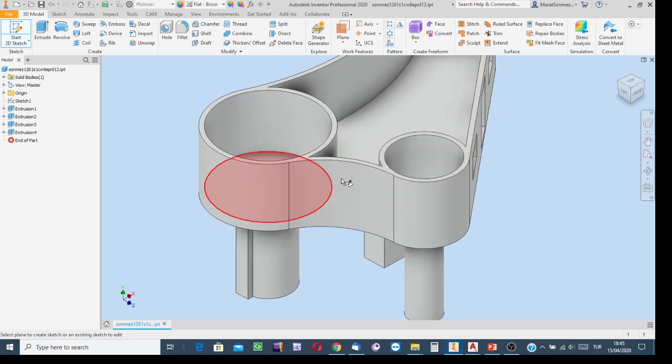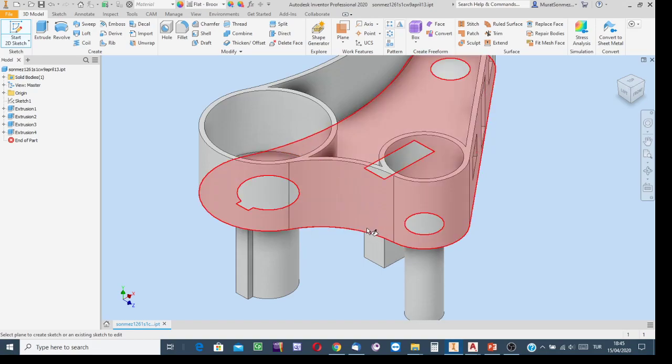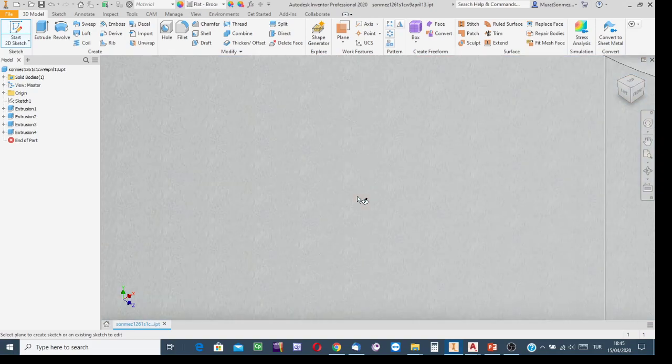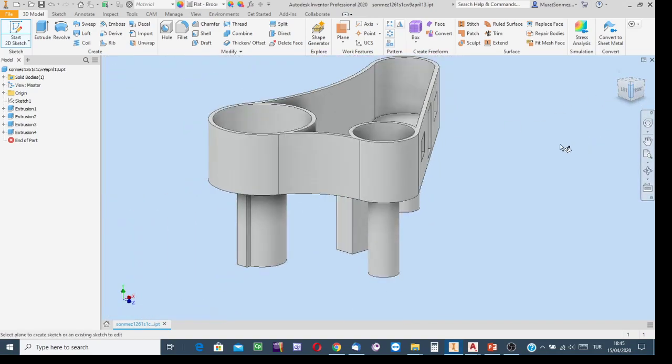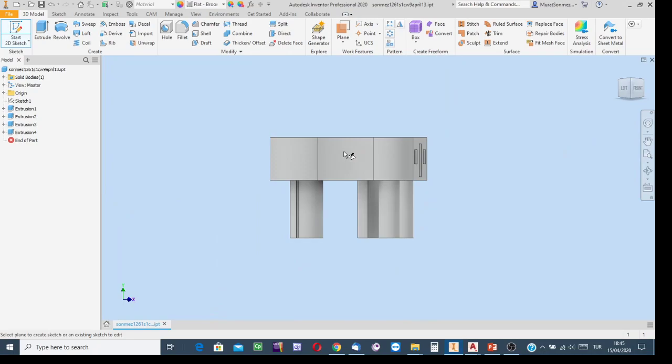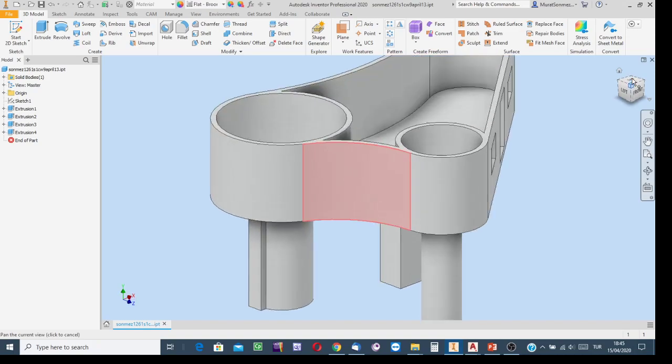Okay, it cannot find the sketch plane because the surface is a curved surface. If the surface is not a flat surface, you cannot simply indicate it. You say I broke the cursor and keep repeatedly clicking the mouse. There is no response. The buffer is still in the 3D environment, not sketch mode. What can we do? Press the escape button because going ahead is impossible. Now,